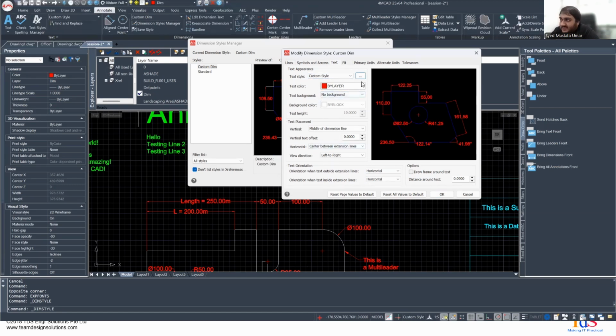There are a few settings for that text that are already there, sort of imported from the text style, but then some are there as such, like text color, the background, the height. If you're creating a new one, this height will be variable, as in you can go ahead and change it. Since I'm modifying it, it's a bit different.